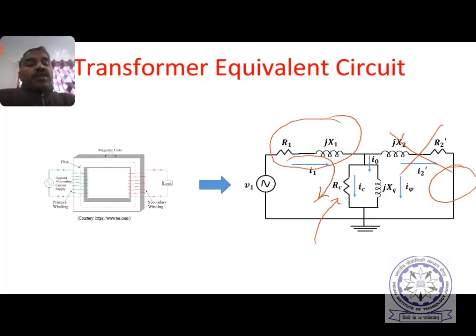Therefore, the winding and core act as two electrodes, and there is a dielectric between them. So definitely that will act like a capacitance, right? Of course, it is a distributed capacitance, but you can consider an overall capacitance between the winding and the core. So there must be some dielectric losses associated with that. So there are dielectric losses.